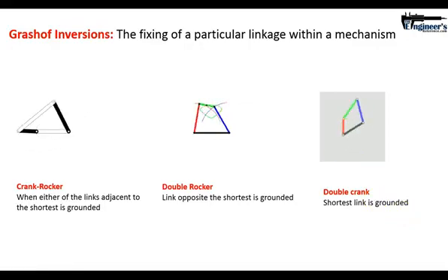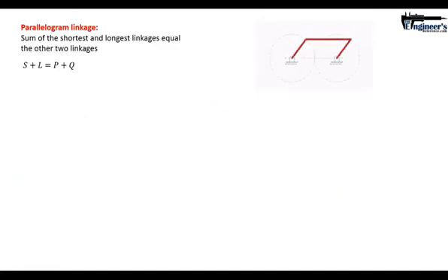So we've covered how the lengths of the linkages affect motion, as well as how the configuration of the linkages can affect the motion. Now there is one linkage, a non-Grashof linkage, that I want you to take into account. This is where the sum of the shortest link and the longest link are actually equal. So S plus L is actually equal to P plus Q. And you end up with this particular position, which is just a parallelogram linkage. You can see you're seeing a complete motion in this particular picture, but that's not always the case.